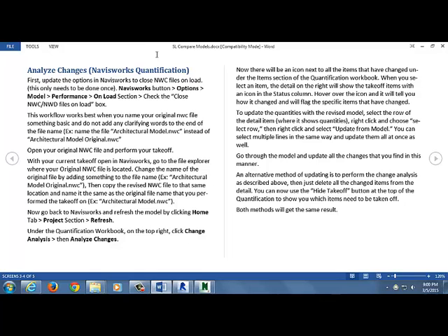So now, the second paragraph on the right, you select the row of the item that's changed. So if you hover over that little, just hover over it. So it said it changed values. So if you click anywhere on that row, which you already did, now right click, say select row. You have to select the row where you make the changes. And now right click again, and say update from model. So now it updated. So you see that value changed.